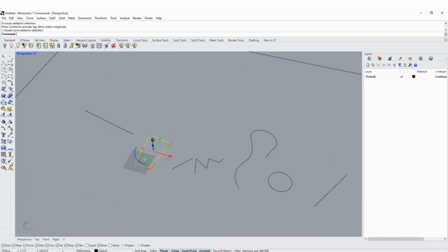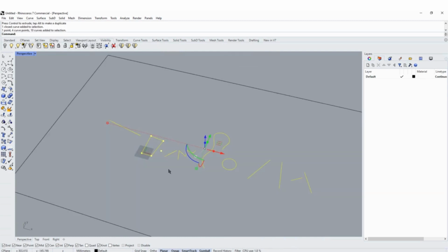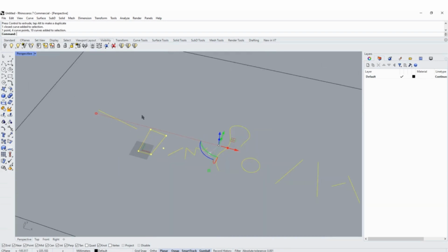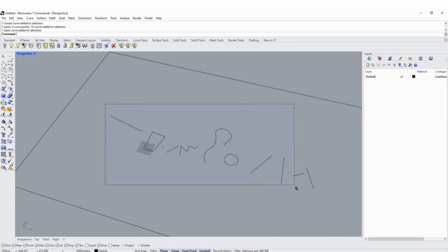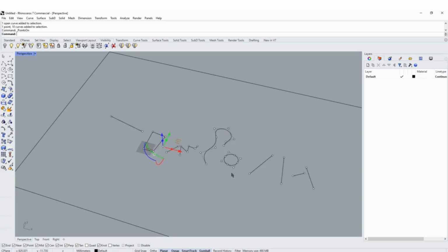And as well, the control points. All of these elements are defined by control points. Let me select the elements, you see? They're all defined by control points. Sometimes, for example, if I select this one, I see it directly. But sometimes not. Sometimes they're just highlighted yellow curves. But I really want to see the points. There is always an option, follow me. It's right over here. So show object control points. I click that, and now I can see all the different control points.